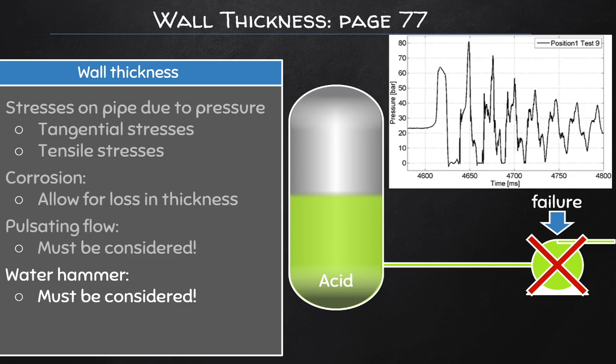It will, and you have to deal with it. Now, a control valve can also induce such variances, and what can happen is when the failure occurs, if there's a sudden loss in power, for instance, a pump could stop suddenly, a valve could close suddenly, creating what is known as water hammer.